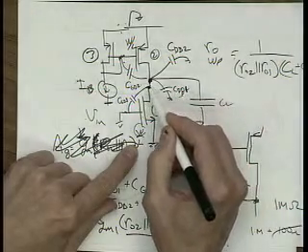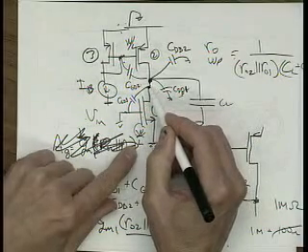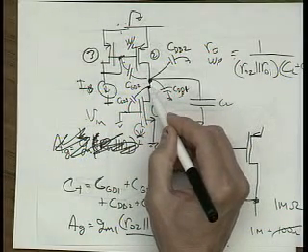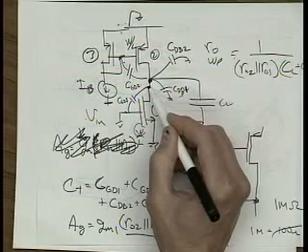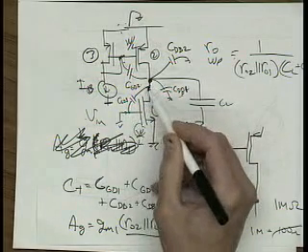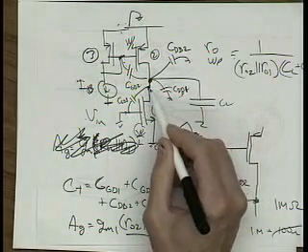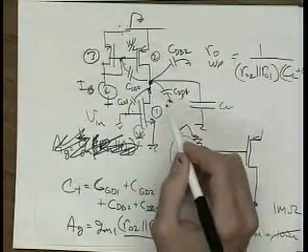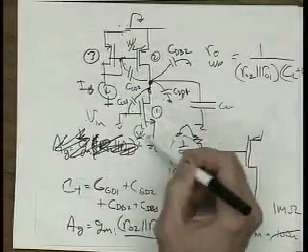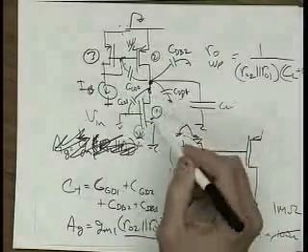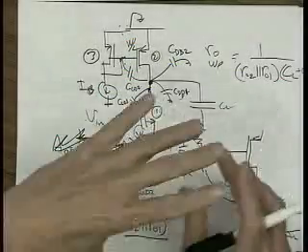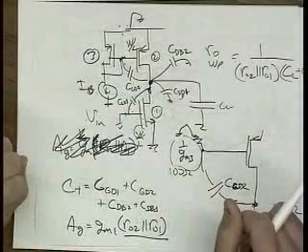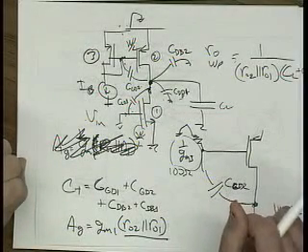The drain capacitance on this node will get really large because they have a really big drain region. Also, the CGD1 will also get bigger when I make this transistor have a really big W over L. So both these capacitors will get a lot larger when I try to increase the W over L of this transistor to get more gain. So again, you sort of see this. There's a fairly fundamental relationship in these things that you end up with.